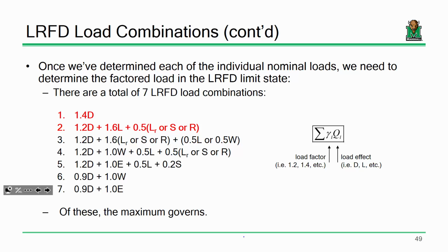Exactly. If I go back to my table analogy and look at this table from a dead load and live load consideration, I could compute the dead loads pretty easily. I could just put it on a scale and weigh it, and have reasonable certainty that those loads are correct. Even without the scale, this is wood with these dimensions, so I could compute it. I'm an engineer, so I should get pretty close. I may not be super exact, but I'm going to be pretty close.